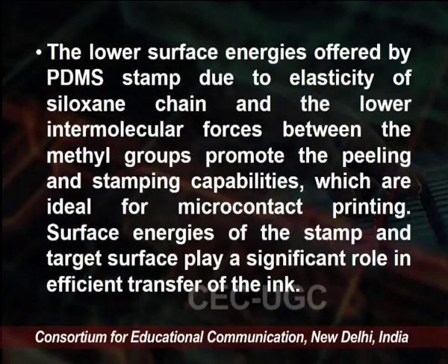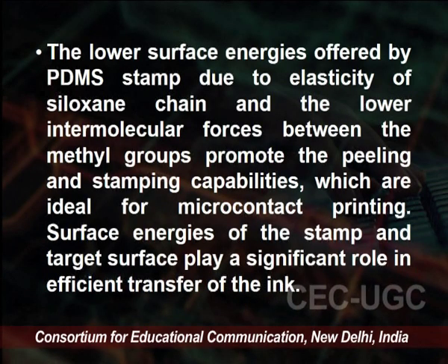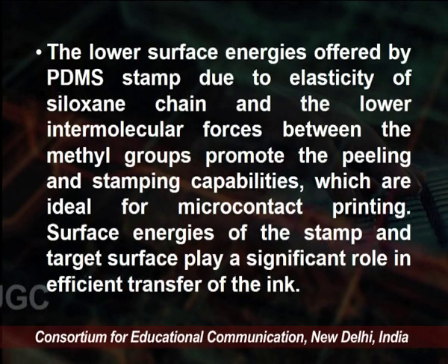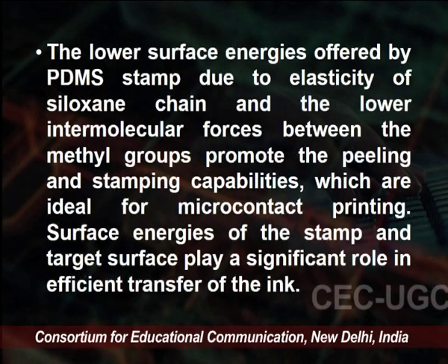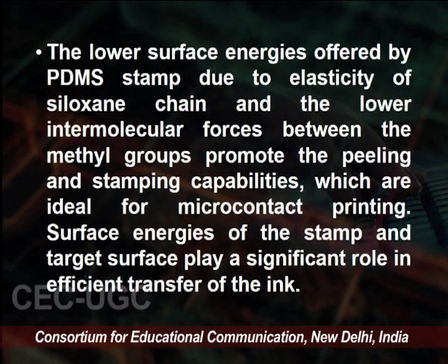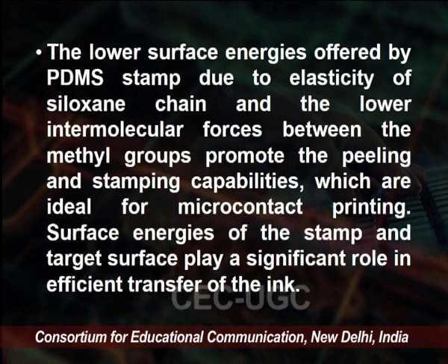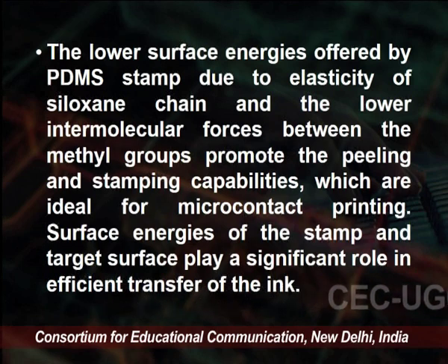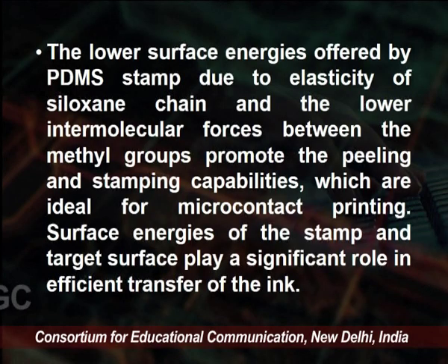The lower surface energy is offered by the PDMS stamps due to the elasticity of the siloxane chain, and the lower intermolecular forces between the methyl groups promote the peeling and stamping capability, which are ideal for micro contact printing. Similarly, the surface energies of the stamp and the target surface play a significant role in efficient transfer of the ink.